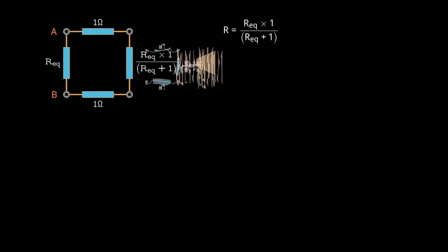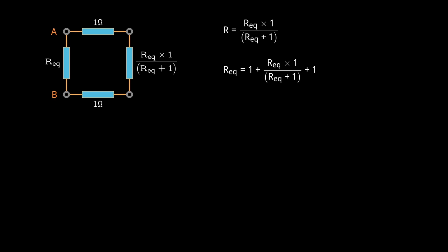To find an expression for the equivalent resistance, we begin by simplifying the circuit. First, we replace the two resistors in parallel with their equivalent resistance. Then, we combine this result with the other resistors in series to determine the total resistance. This total resistance represents the equivalent resistance of the entire ladder, which remains unchanged due to the self-similar nature of the infinite ladder circuit.